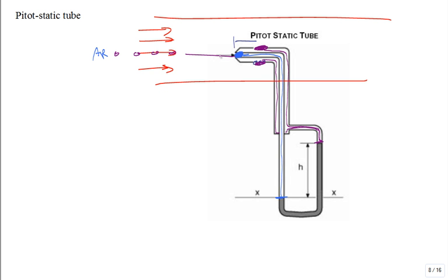And one unfortunate little pack of fluid going straight there, when he hits it, he comes pretty much to rest before he turns the corner and gets around it. Okay? So the kinetic energy of that pack right in that vicinity goes to zero. I know it doesn't go perfectly to zero, but it goes essentially to zero, and then it slides around the side. Okay.